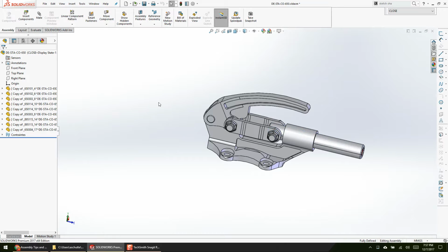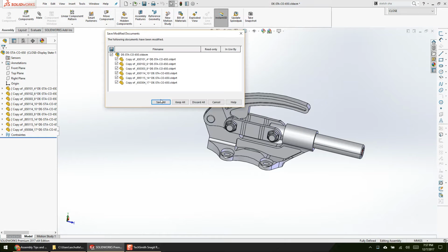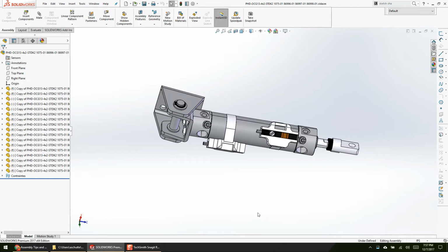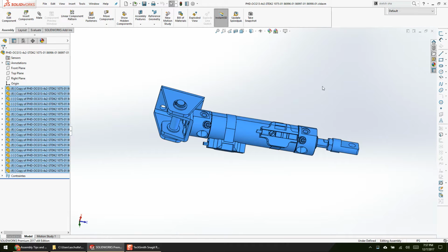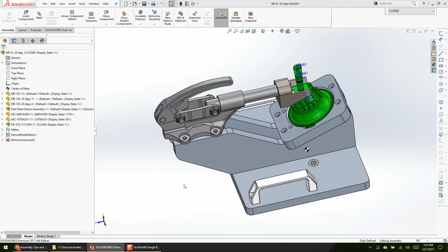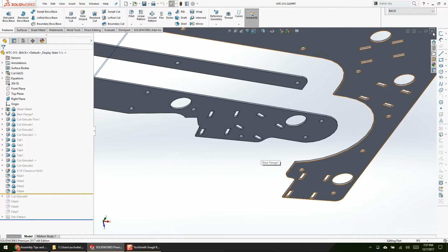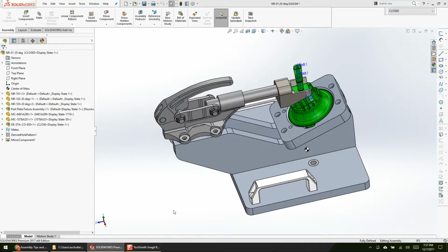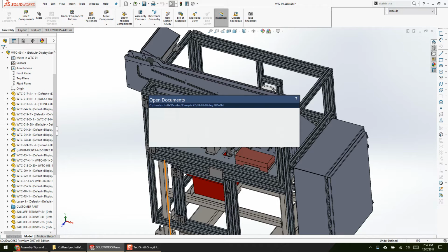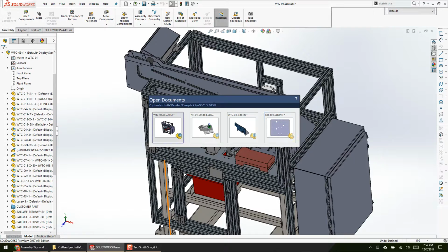So the virtual components are fantastic for purchase commodities in instances in which we do not need the components. And that's what I did here. So this assembly here contains all of those parts. So I only have a single file on my hard drive that I'm managing. So back to... So do those virtual parts end up in the bill of material? Yes. They are every bit a part.